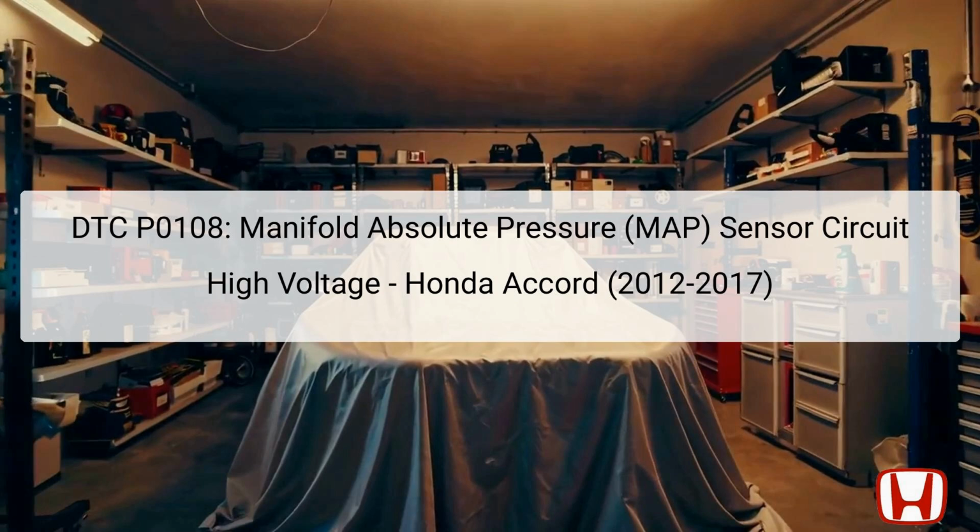When voltage levels exceed predetermined limits, the PCM identifies this anomaly as a malfunction and subsequently triggers the DTC. Understanding this diagnostic code helps in pinpointing issues that may impact vehicle performance and fuel efficiency. The MAP sensor's location is typically near the intake manifold, ensuring accurate pressure readings for the engine's operation.